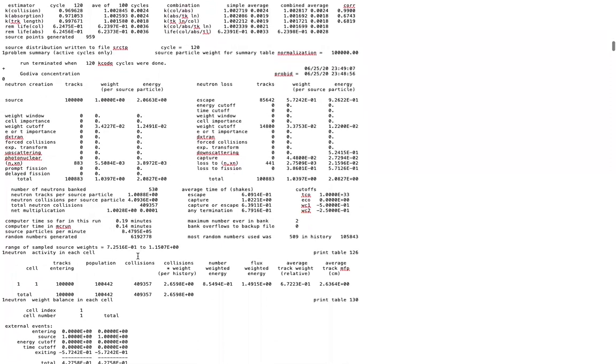Now let's see the summary. Now on the summary, you see one side over here and one side over here. So this is the creation side, and that's the destruction side. What was created? Let's see that we started 100,000 tracks, right? 100 cycles, 1,000 each. The weight we gave to each was 1. The average energy was 2.0663 MeV. And the weight cutoff, when there are more and more collisions, so it used a weight cutoff like this. I didn't tell it to, this is defaulted MCNP.